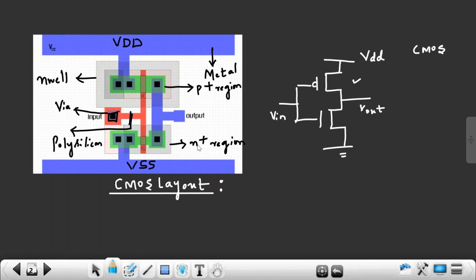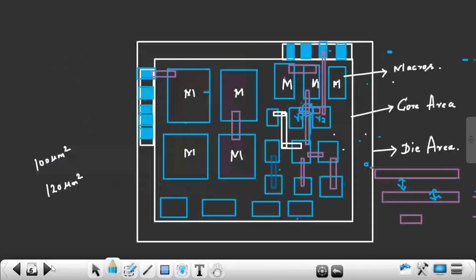So remove all these layers and only load the required layers, because anyhow I'm not going to touch these base layers during physical design. Otherwise the memory and runtime of the tool increase. So we use only the layers required for PD, which are present in the LEF file. So we call LEF abstract layout information, not complete layout information.